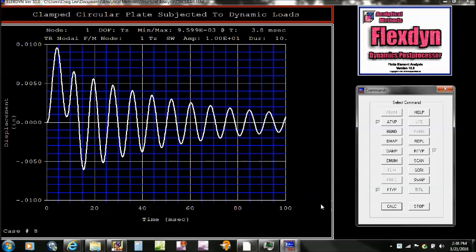And here's the time history of the response of that plate. So a lot of ringing. It's 2.5% damped, so you could calculate what that is from the decay here. But you can see that the maximum is about 1 mil, I believe, or 9 mils, I'm sorry, is the maximum displacement there with that shock. And you can see the time duration, and so on.